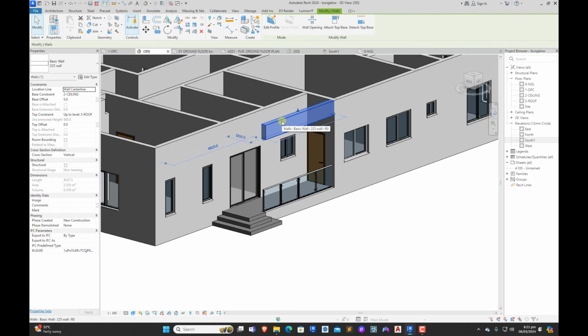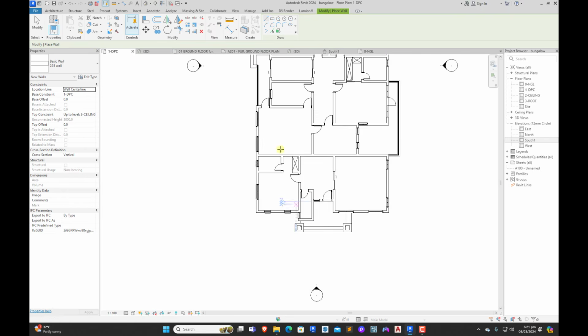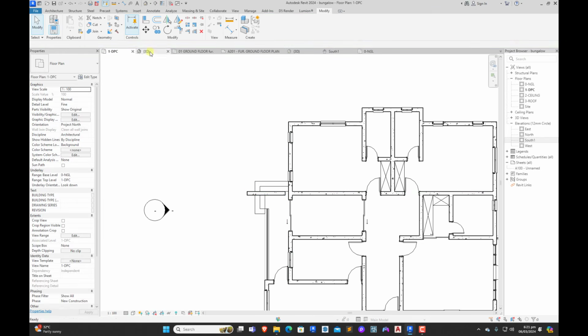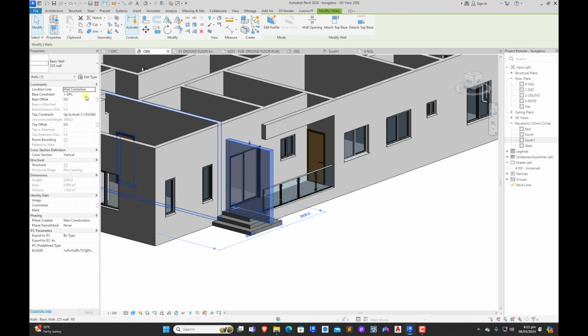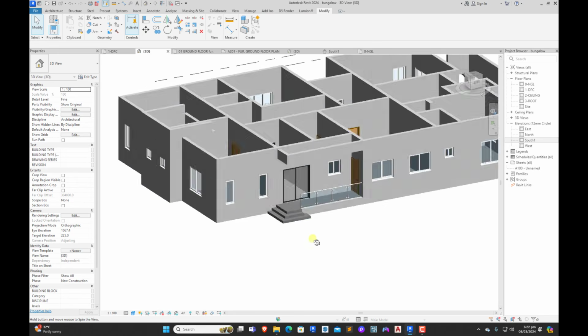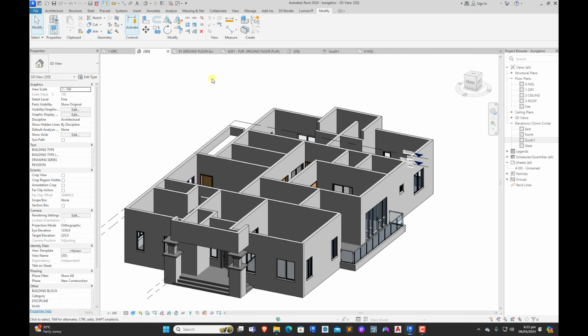We click on this CS. We'll come to this point, and we draw another wall right here. With this, we can do the same thing, ceiling level and roof level. Then we use our trim to trim both of them. Perfect, so this is done. We come to this place to do the same thing, create our beam for this point.